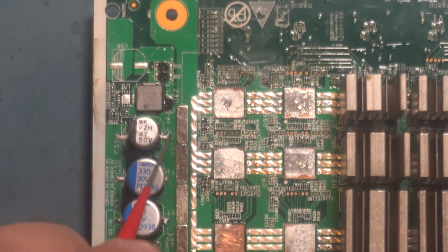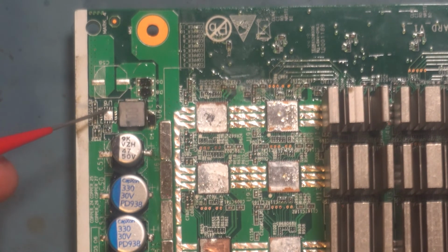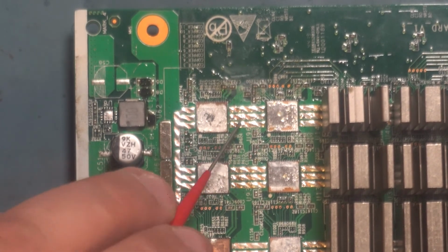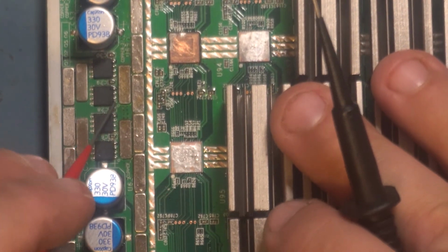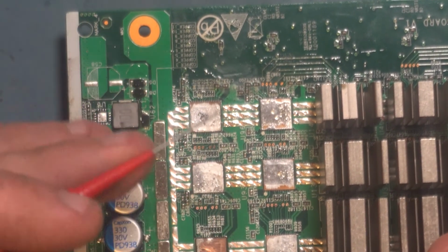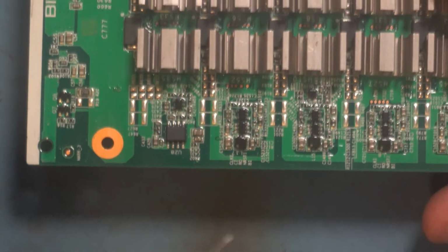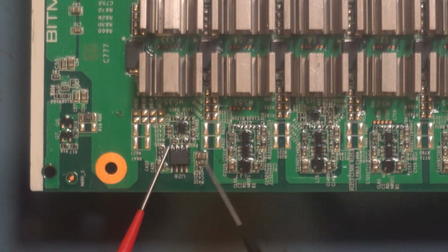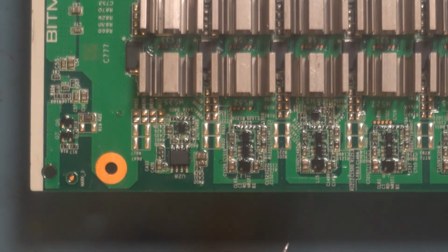So it's to take whatever comes out of your Mosfets, your 24 volts or whatever, boosted by a couple more volts, and then use that higher voltage not to feed the chips, because we know the chips are already fed by these traces, which are directly fed by the Mosfets, but that higher voltage is going to be used as a voltage with even more headroom to then go into your LDOs in your last couple domains and be used like that to generate your 1.8 volts and your 0.8 volts for those domains specifically.